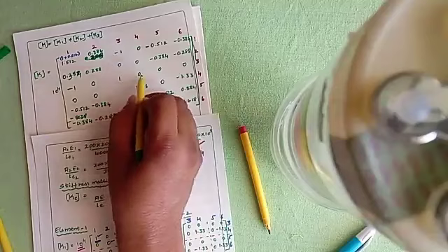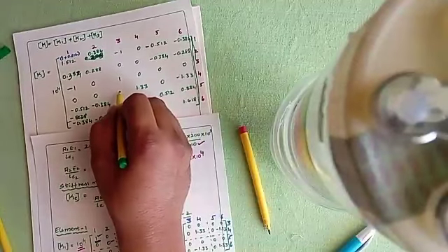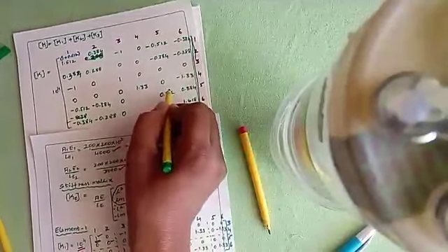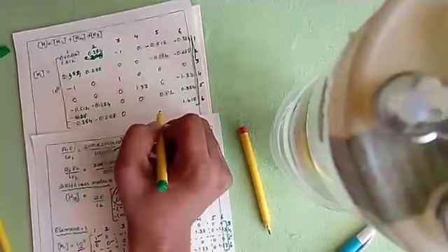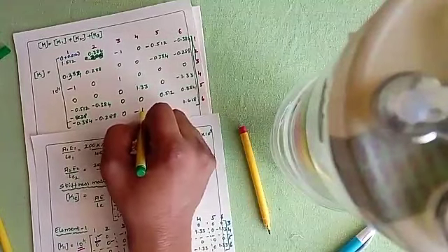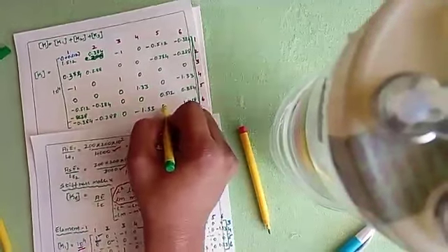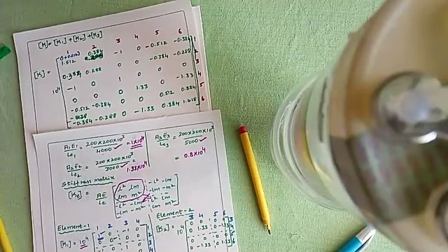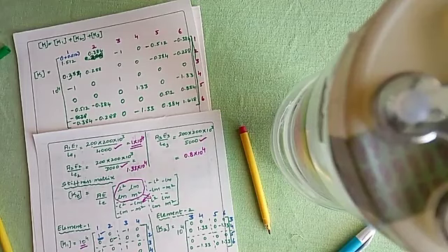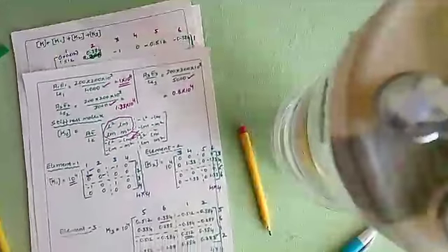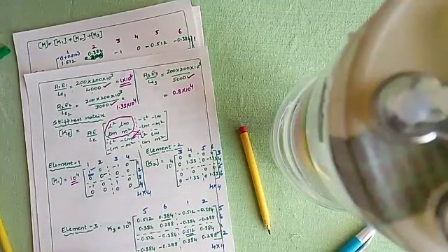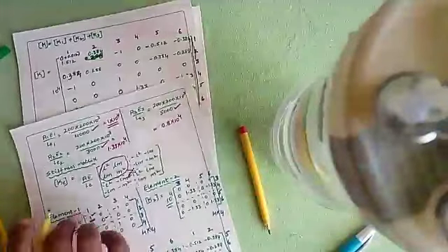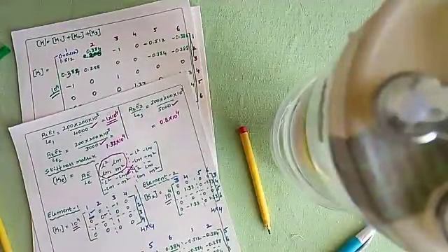Okay, 1 0 0 you have. Next I'm going to replace 0 0 0 over here. 1.33, minus 1.33, 0, 0.512, 0.384, minus 1.33 and 0.384. Okay, this is how you are going to form a global stiffness matrix. You need to look into these three stiffness matrices and you're going to form a global stiffness matrix. And out of all the three, 10 to the power 4 is common. So that 10 to the power 4 is being written over here.